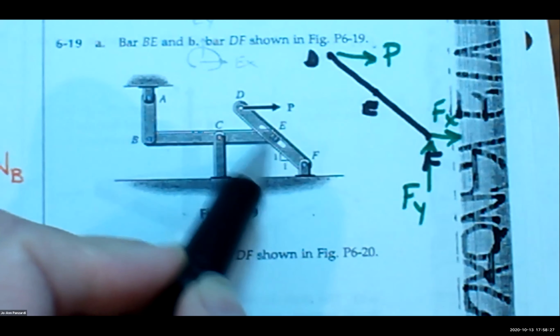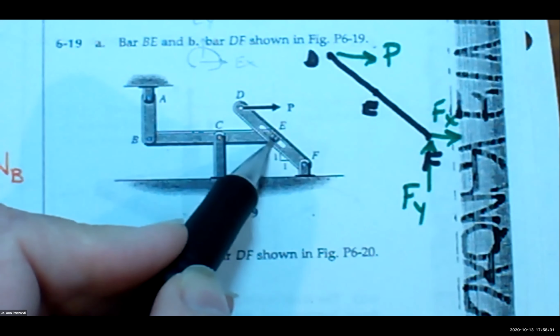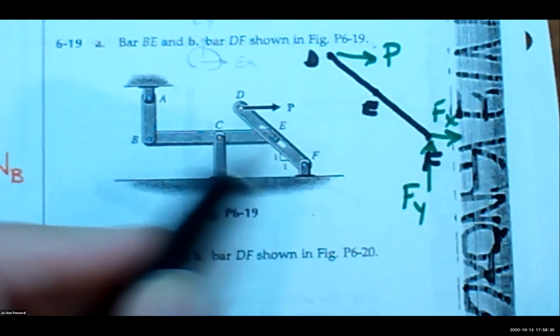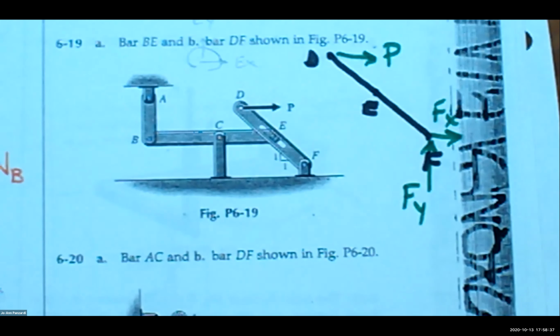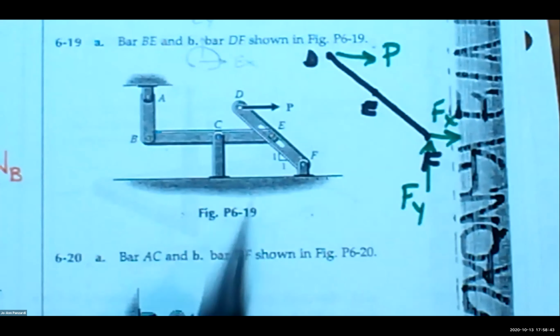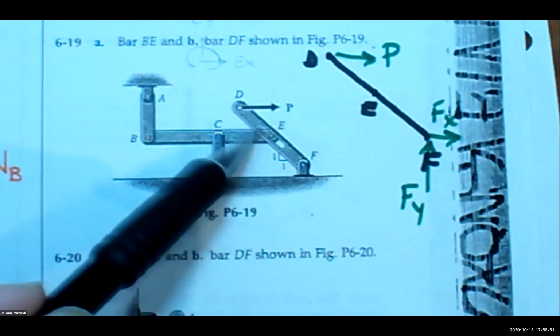This rod could move in here. So if you look at these two rods relative to each other, if you had an erector set, a rod and another rod, and there was a slot in here, can these rods move relative to each other in this direction, Tim? Yes. So that means it does not resist it, so there's no reaction that way.